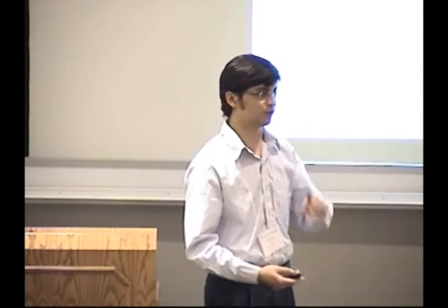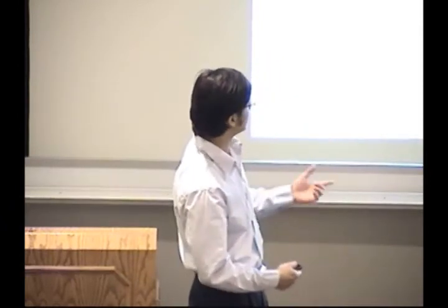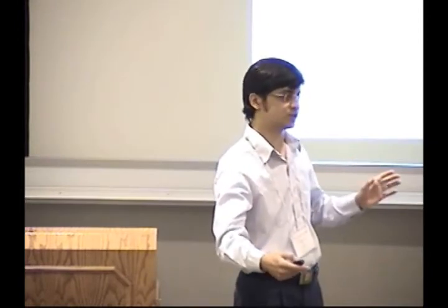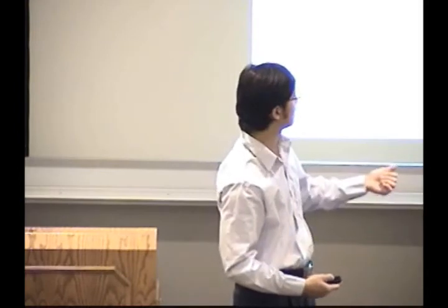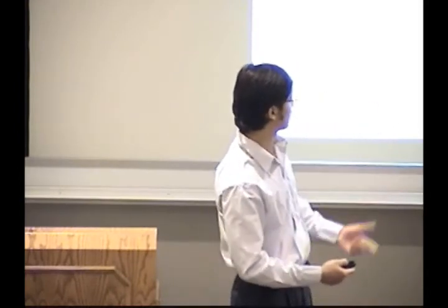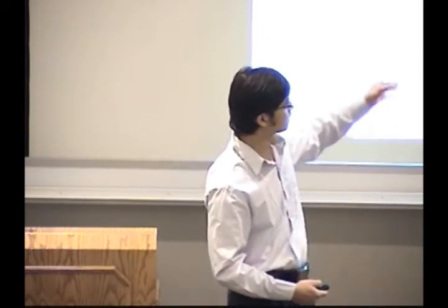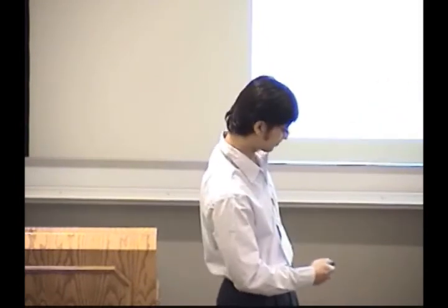A blade essentially is a wing, except it's placed in a different orientation. In diffusers, you have a reduced pressure recovery. Pressure recovery basically is the ratio of the total pressure at the compressor stage to the inlet stage. It's the amount of pressure energy you have recovered from the kinetic velocity energy of the complete flow. That goes down, and you have increased distortion and turbulence at the fan face, at the compressor stage.